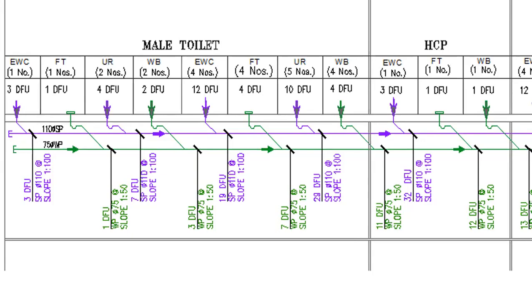If you are taking a 70 mm waste pipe, you can provide 1:50 or 1:70. In our table we found 1:50, that's why I have provided a 1:50 slope. You can go up to 1:70, either 1:50 or 1:70, based on your available site conditions. Normally we will go 1:70 for the waste pipe. So we are connecting into the 100 mm soil pipe header.